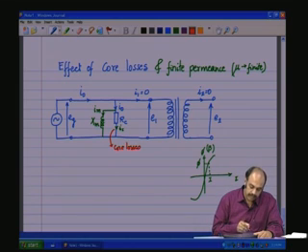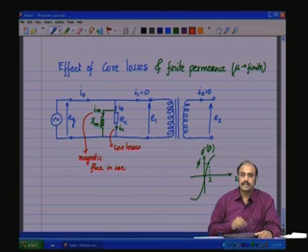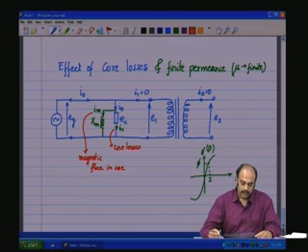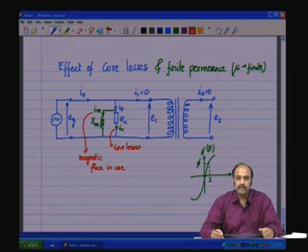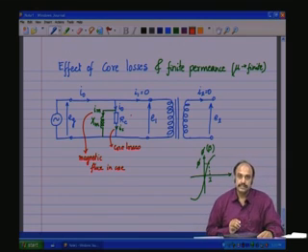Im is that component of I naught which produces the magnetic flux in the core, such that it can be linked to the secondary and have an induction on the secondary side. So, these two non-idealities result in such an equivalent circuit.